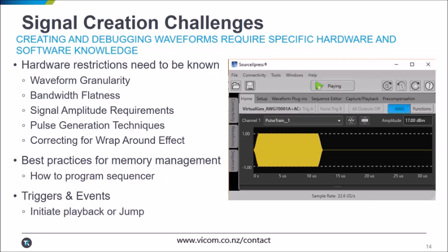spurs and phase mismatches. Other challenges are encountered when building sequences, which is basically a playlist of waveforms that can be accessed through an external trigger or dynamically while the sequence is playing. It is also important to know how the trigger system works, and when a trigger arrives, how long it propagates through the system and a waveform is played out of the actual analog channel, and how repeatable this is.